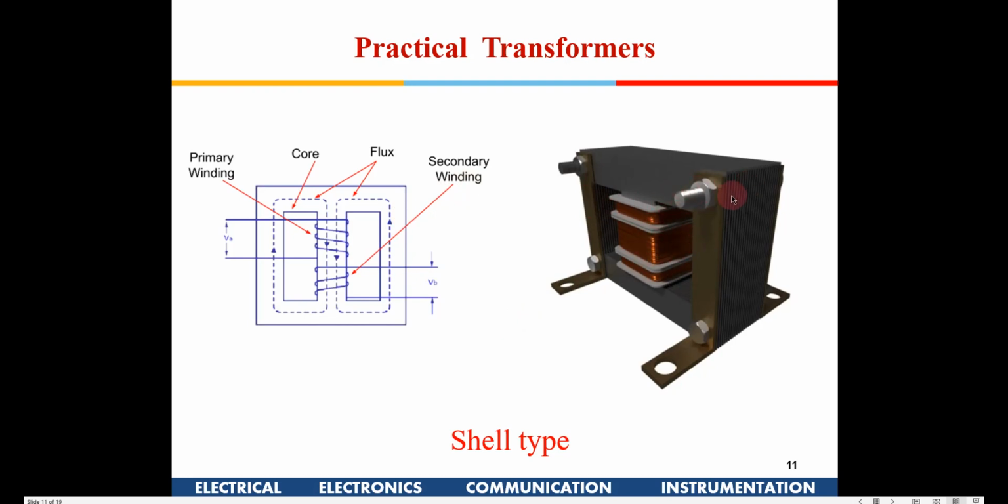Okay, so you can see here, this is not a single metallic block. This core is made up of a large number of thin metallic sheets which are insulated from each other, because each sheet has an insulator coat, usually a varnish or a plastic coat above it, and then they are placed together. So magnetic-wise they act like a single block, whereas for electrical currents they are not, so that will prevent huge currents flowing in these blocks.